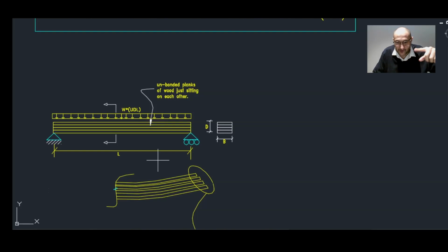And because there are varying bending moment values, there will be out of balance forces, and the difference in the moments is going to be balanced by the horizontal shear stress. Okay, we will go through it step by step and see how this all works out.